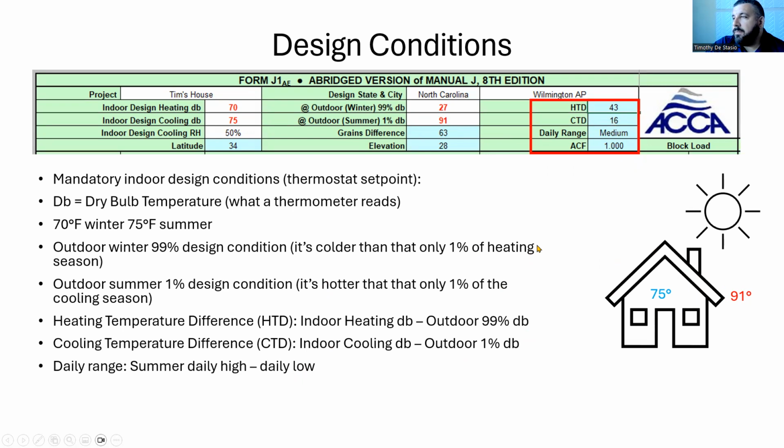And so your daily range is going to be higher than if you lived elsewhere. So there's a pretty big difference between a house that cools off, let's say, to 75 degrees at night, where you're not really exchanging a lot of heat, but if it cools off to 65 degrees at night, you actually start giving some heat back. And so it does make a difference as far as how much air conditioning you're going to need the next day. And then altitude does matter.